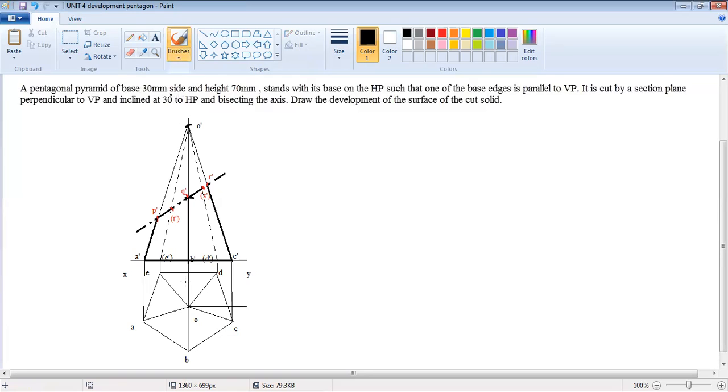Okay. Place the compass in this O point and measure this C and cut an arc, draw an arc like this. Okay. If we have any horizontal line, we can directly take the particular edge.